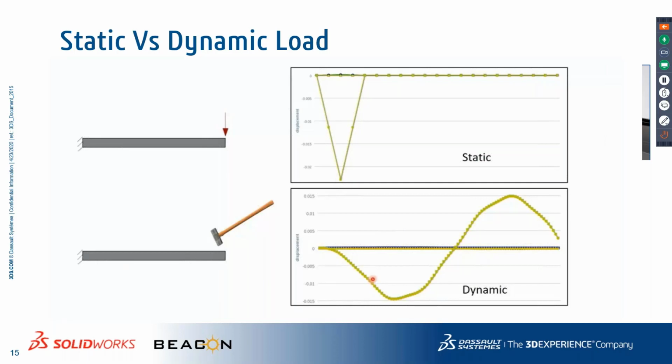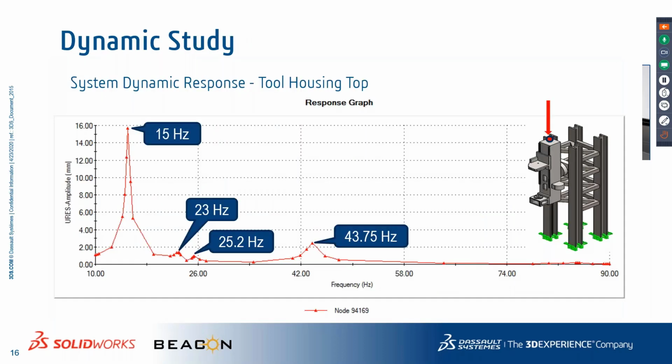Okay, and when you see that only static analysis is not sufficient for this kind of application, we also need to understand the difference between static load and dynamic load. To consider the effect of a dynamic load, we have very good solutions in terms of frequency response analysis, like harmonic analysis, random vibration analysis, and shock vibration analysis, to understand what happens if your structure meets the resonant frequency. What dynamic stresses are going to come onto your structure can be evaluated using the vibration analysis capabilities present in SolidWorks Simulation.